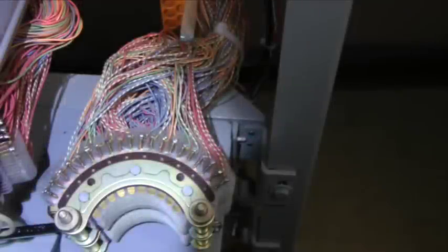With the connector switch removed from the demonstration unit, we can now have a good look at the connector bank wiring. On this bank assembly, each circuit consists of 4 wires, one of which we are not using, so we will ignore it. The other 3 wires are the tip, ring, and sleeve. There are 100 sets of tip, ring, and sleeve leads cabled from this connector bank over to the intermediate distributing frame, where they terminate on telephone number connecting blocks.